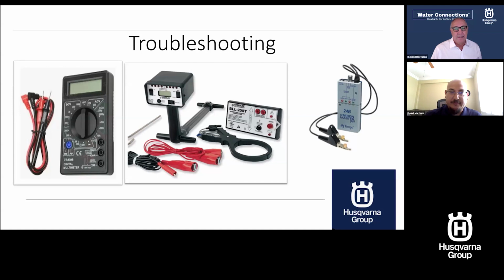If you recall back to one of the previous slides, when the valve box was full of water, this would cause a short because water is going to ground that circuit directly, and it's going to get back to your controller, and then you're not having any water going through there. So we want to make sure we resolve these issues before they get out of hand.